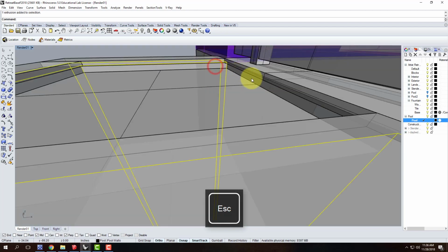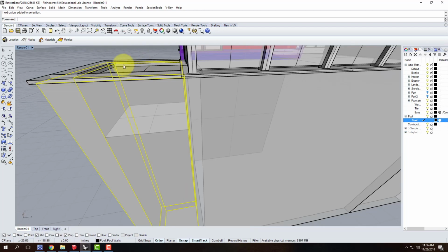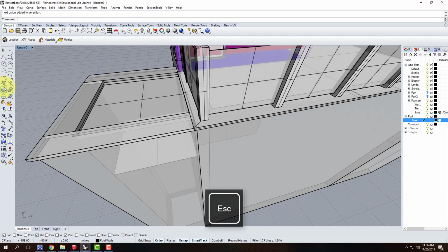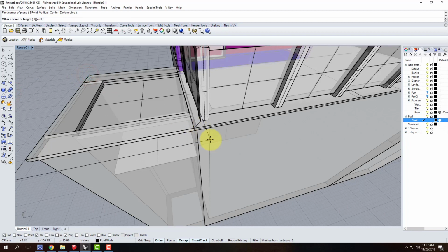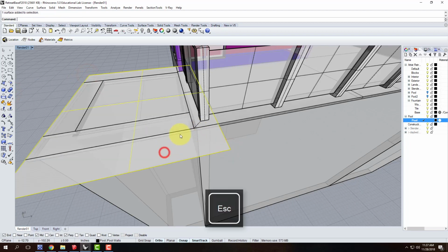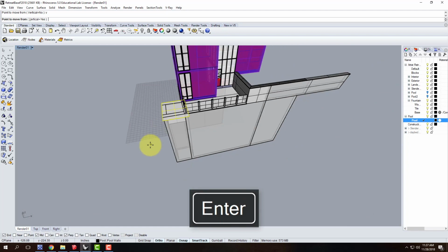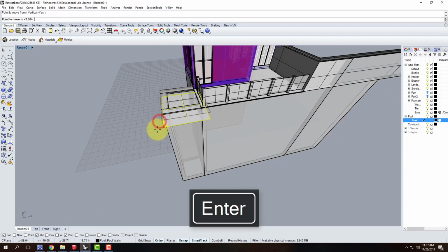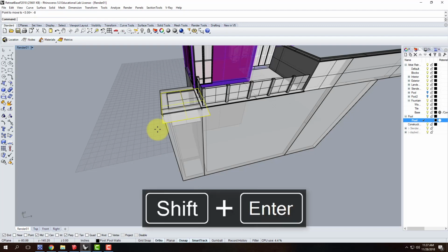The upper part of this probably should be tile or something. So let me go ahead and add another surface here. This one will be larger. We'll move this vertically negative 8 inches to get it below the surface of the water.